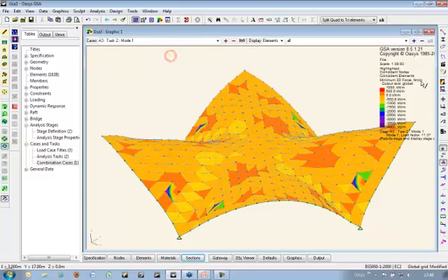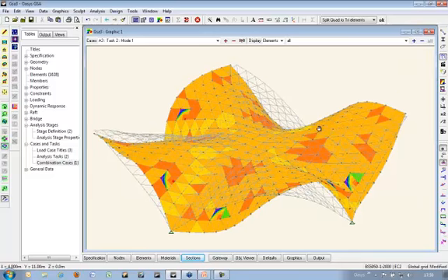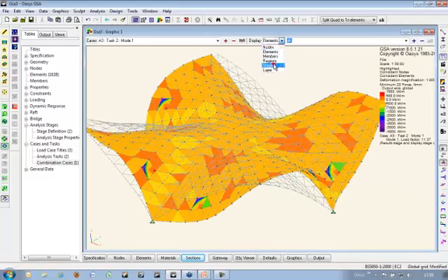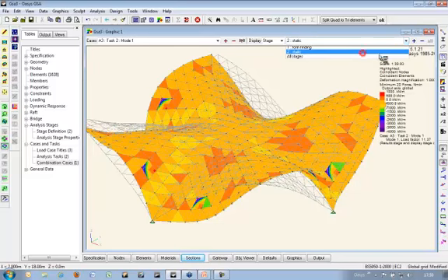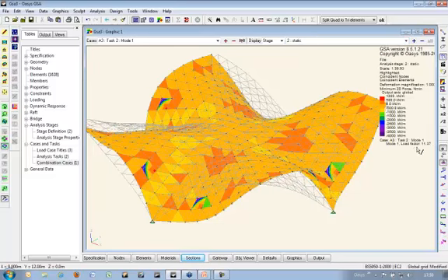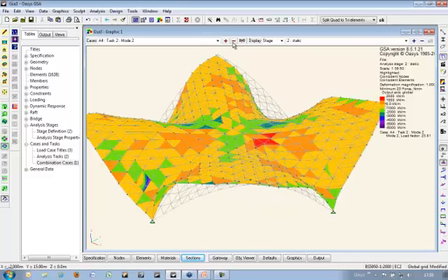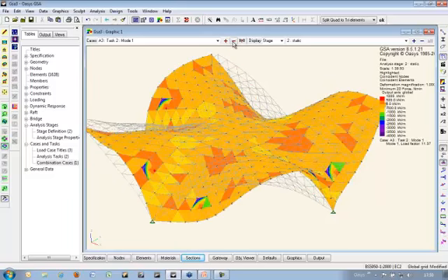And well, let's look at the deflected shape, and we can see the load factor here is 11.4, so it would take 11.4 times the applied forces to actually make this shell buckle. And the next factor 23. Bear in mind, of course, that asymmetric loads can govern the design, so you need to check for wind, snow drifting and that sort of thing.